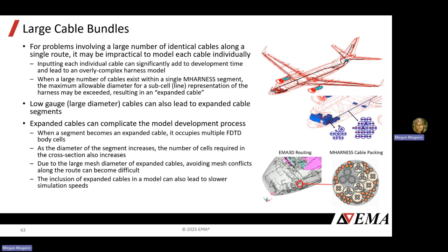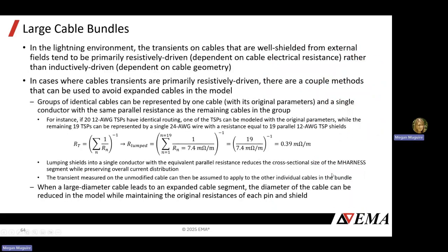I'll get into some things that you can do to try to reduce the size of these bundles, which is really only applicable in low frequency environments. So like in a lightning environment, transients on cables are well shielded, and also transients are primarily resistively driven rather than inductively driven.